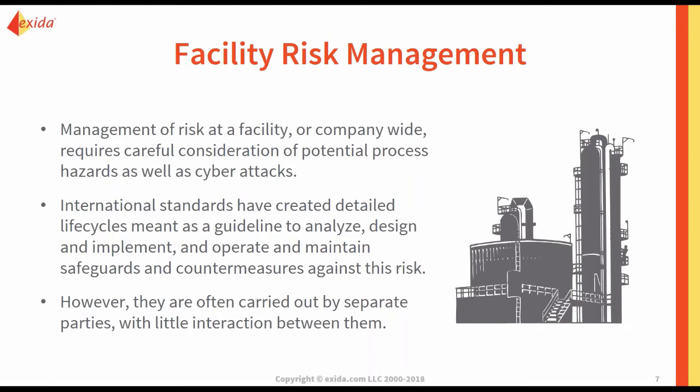How do we guard against these cyber threats? We have IEC 61511 for functional safety, and we have IEC 62443 for cybersecurity, and they're meant to analyze, design, and implement safeguards and countermeasures against these risks. But they're often carried out by separate parties with little interaction between them. So the methodology we're going to talk about today is basically going to try and open the lines of communication by leveraging best practices used during the functional safety lifecycle to also address your cybersecurity risks.